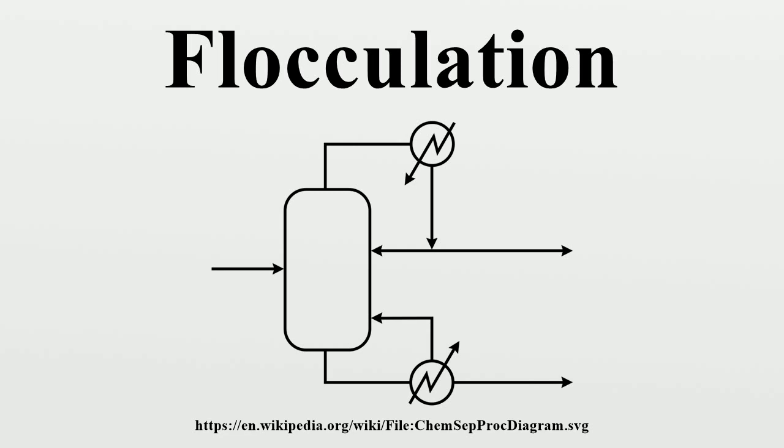Deflocculation. Deflocculation is the exact opposite of flocculation, usually in higher pH ranges. In addition to low ionic strengths of soil solutions and domination of alkali metal cations, the soil colloidal particles can be dispersed. The additive that prevents the colloids from forming flocs is called the deflocculant.